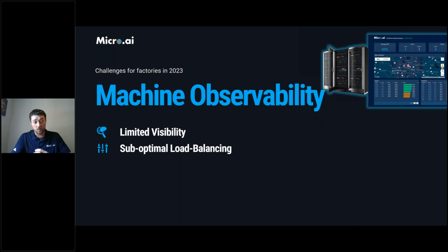Another area that we've noticed a lot of people are having problems with is suboptimal load balancing. So when I say that, I'm meaning a reduced productivity based on, let's say, a starved block condition where you're having a lot of high cycle time issues, or maybe you don't have your buffers placed in the right area, or you have an operator not working at the right station.